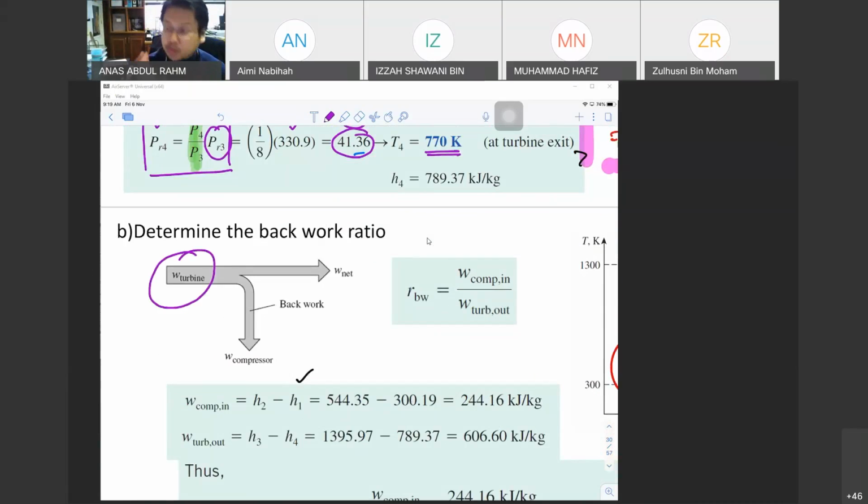It's being split into two. Satu ialah untuk power up the compressor. The other one is W net, which is basically connected to the shaft lah. So basically, almost half of the power, in theory, from the turbine is being used to compress the substance or working fluid. Okay, only half, the other half is for the total output W net.